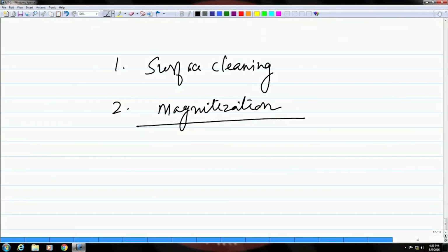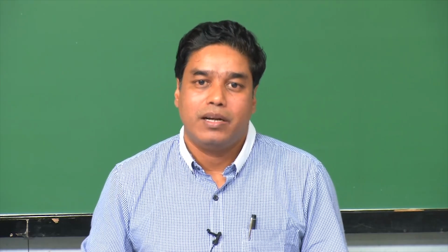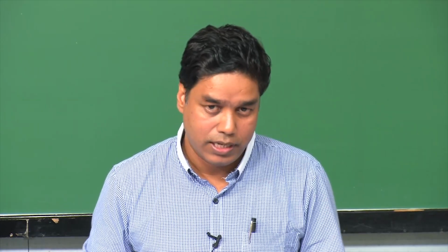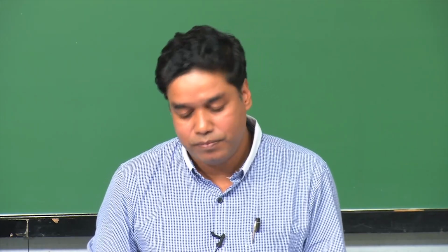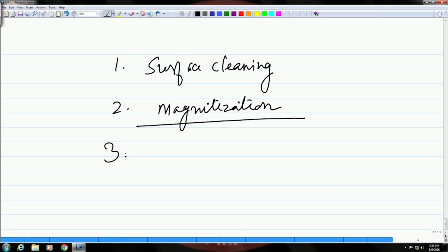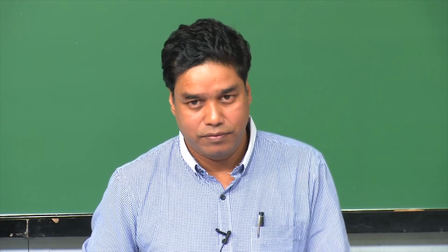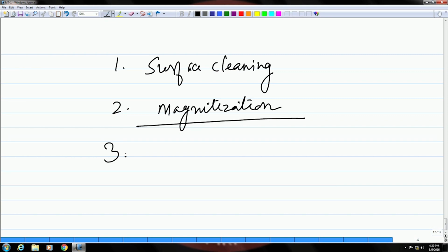So, the next step will be to now apply the magnetic particles. Now, the part is magnetized, and with the help of some kind of field indicators, you have also ensured that the magnetic field is enough to magnetize it. And now, you can go ahead and apply the magnetic particles for them to make visible indications of flaws or defects if they are present on the surface.